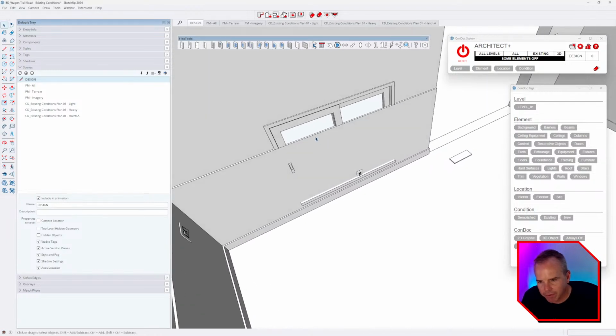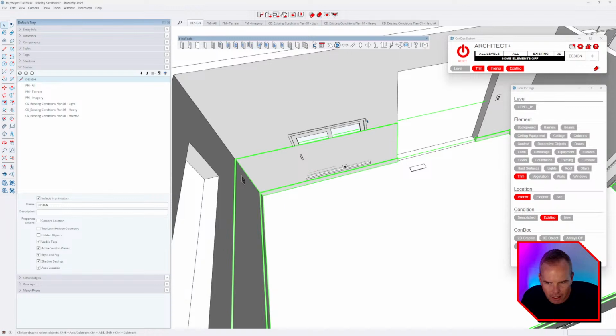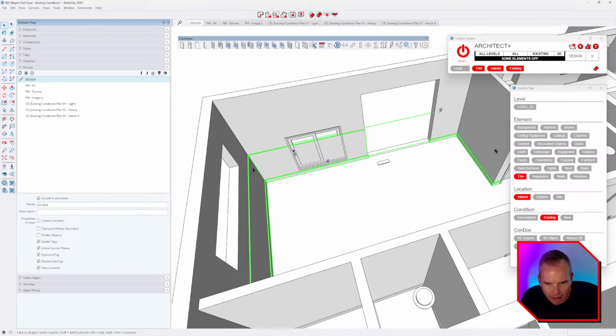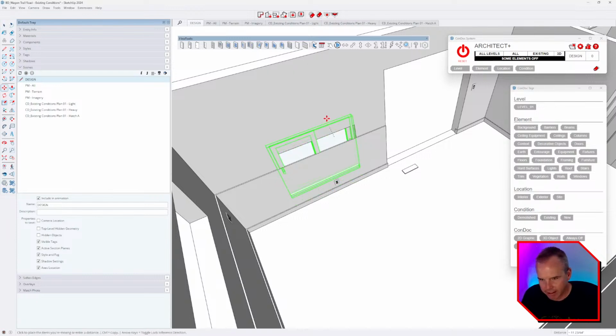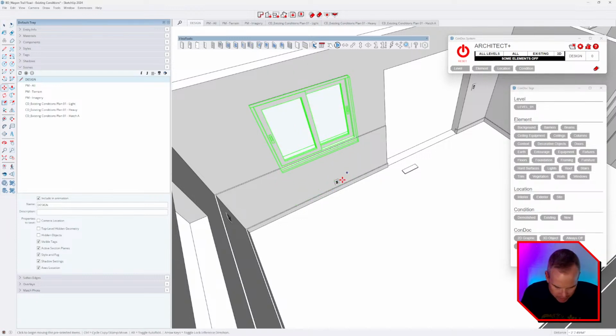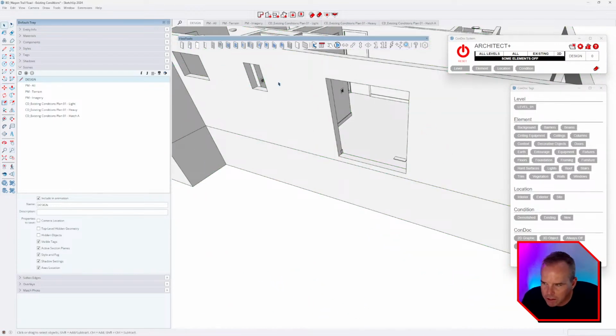And that trim will get demolished, I suppose, which we haven't quite gotten to in our model. That's okay, but you can see what's going on here, that this door is cutting all the way through. Well, for me personally though, I just like to cut my door and window openings because it nets a better, perfect result that's always going to absolutely happen if I just cut the walls myself.